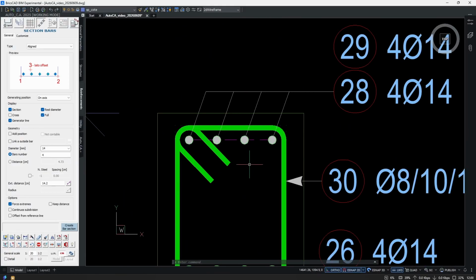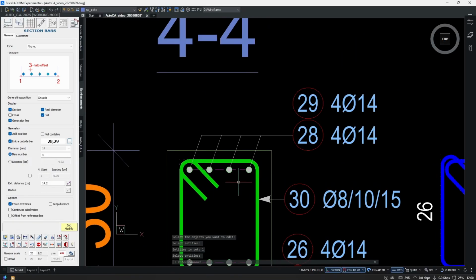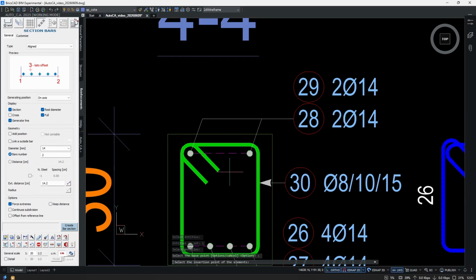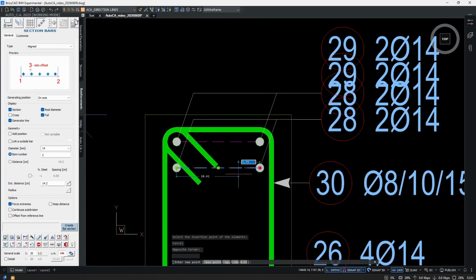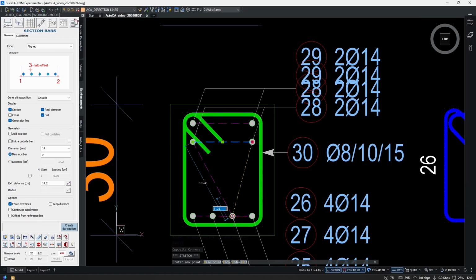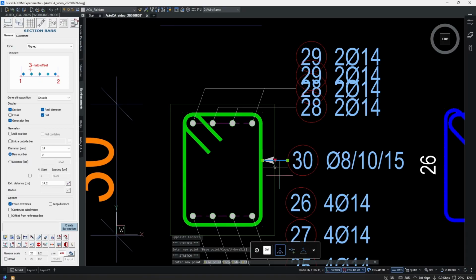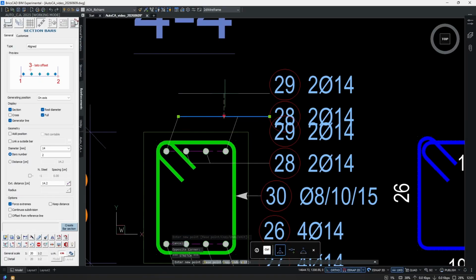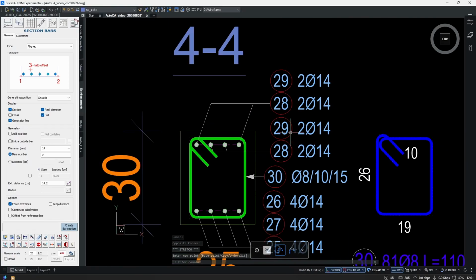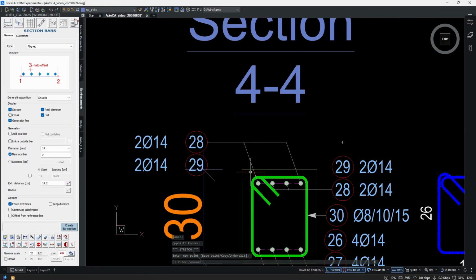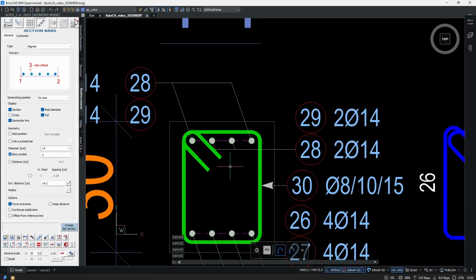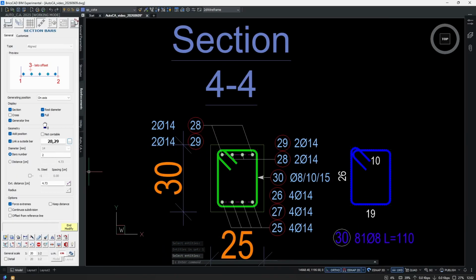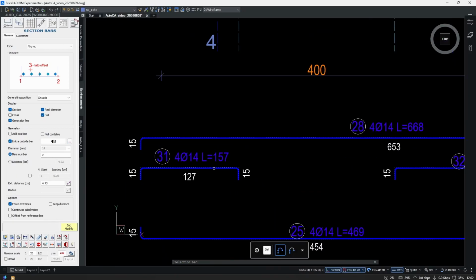So we need to decrease the number of the longer bars, then copy this cross section series. I'm gonna change the position of the bar sections over here, bring it up, bring this callout lower, this one as well. We need space for all 3 marks because we have 3 new bars, and let's assign those new bars to the new bar section series.